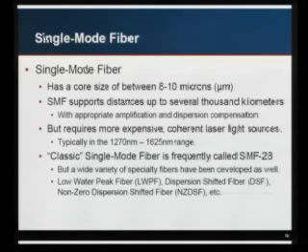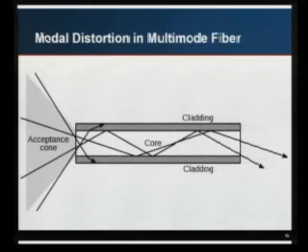And there's classic single mode fiber, which is called SMF28. It's actually a product name, not a standard name, but there's a lot of specialty fibers that go along with that. There's low water peak fiber, there's dispersion shifted fiber, there's non-zero dispersion shifted fiber. There's a lot of specialty single mode fibers.